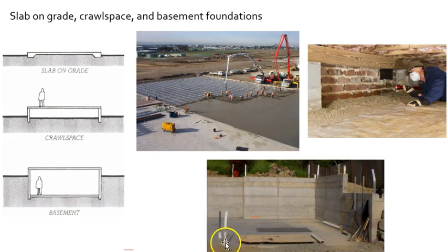These appear to be utilities coming up through the slab, and these are probably tie-down straps to tie the superstructure. This would be called the substructure, and then the superstructure would sit above it. So in areas that are prone to hurricanes, you'd often find large tie-down straps securing the structure, the wooden frame probably, to the actual foundation.